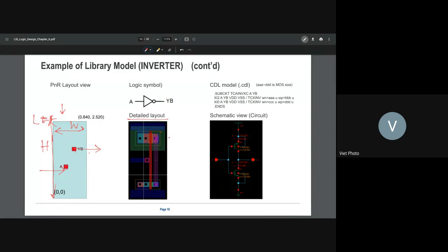It's only when we have some bug or some error that happens in the design. Let's say you have this one, right? This one is the via here, and we put the via outside here, next to that. So it's too close. It causes a design rule error, which is a DRC error.